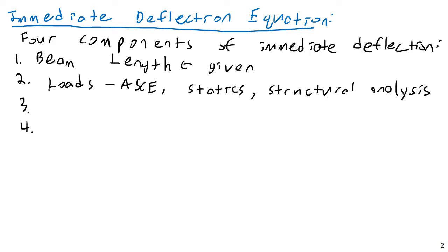So deflection, as we saw previously, is the result, just like a strength design, deflection is a function of both geometry and material properties. So we'll have certain section properties like moment of inertia, and that's a section property of geometry basically. And then we also have material properties. For strength, the material property is yield strength, ultimate strength, etc. But for our deflection, our material property of note is modulus of elasticity. So modulus of elasticity, and we'll talk about each of these things.